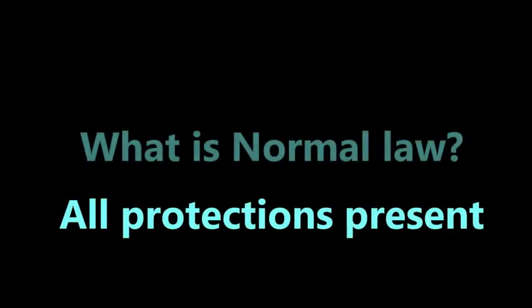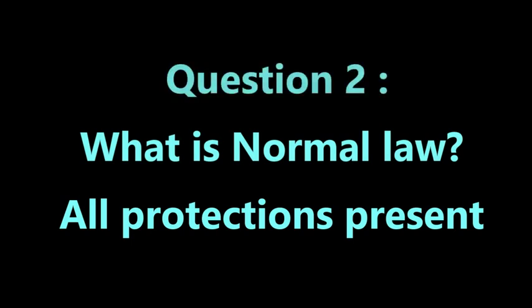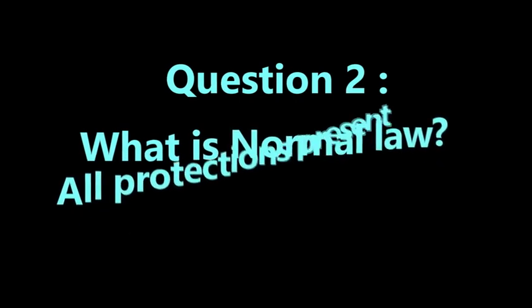This has to do with turbulence and the aircraft computers trying to lessen that feeling of turbulence. But these are just some of those things. So when in normal law, just know that the computers are protecting the aircraft from too much speed, high speed problems, your pitch, basically protecting it from stalling, etc.